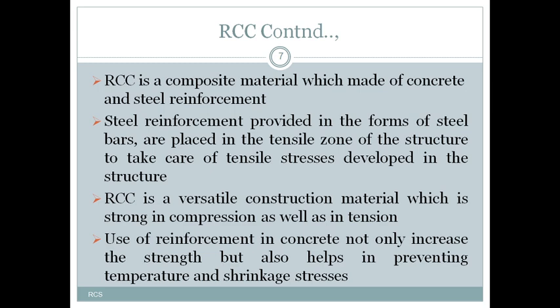The use of reinforcement in concrete not only increases the strength but also helps in resisting temperature and shrinkage stresses. When temperature variation takes place, the RCC member is subjected to tensile stresses.